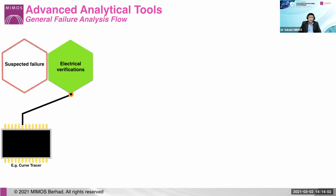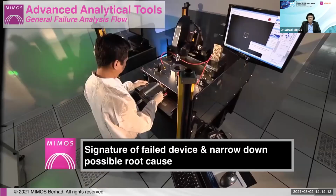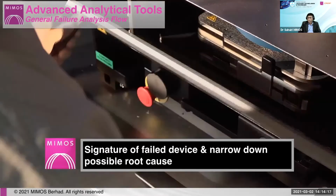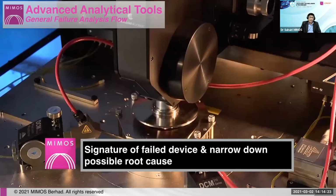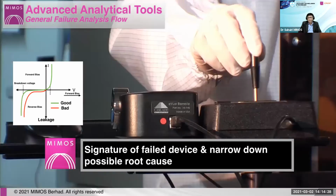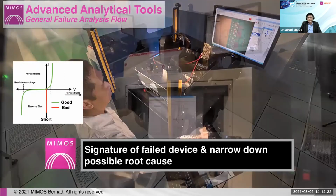And much like a situation when a doctor is presented with a patient's symptom, IC failure analysis begins with narrowing the possible root cause of the problem through validation of symptoms using basic tools such as a curve tracer, which is a common piece of test equipment in the semiconductor industry. And at this stage, the customer will present to us symptoms of failure such as current leakages, open or short circuit, and we will validate that symptom prior to the next action.